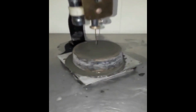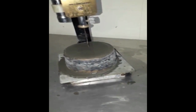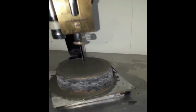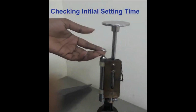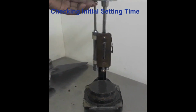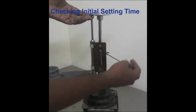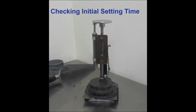The extra cement can be removed with the help of the trowel. Now since the cement is completely filled in the mold, we have placed it beneath the Vicat apparatus and we can see the needle that is used is of 1 mm diameter, which is used for the initial setting time.